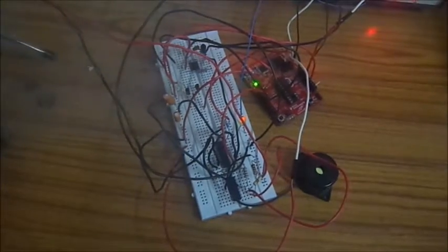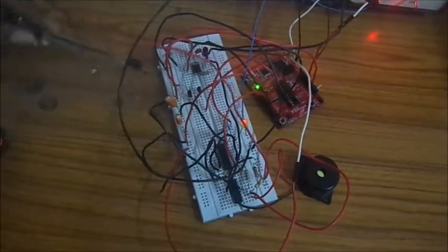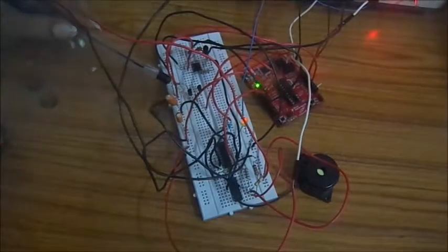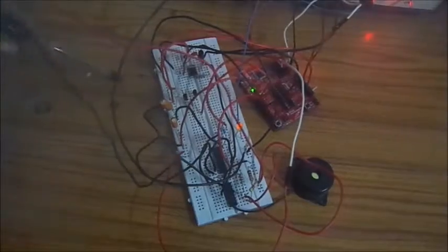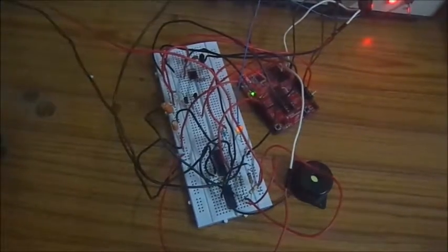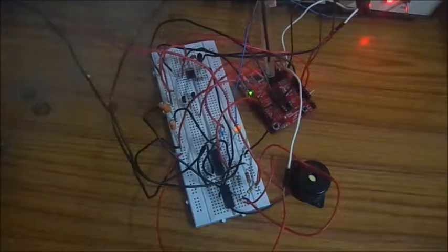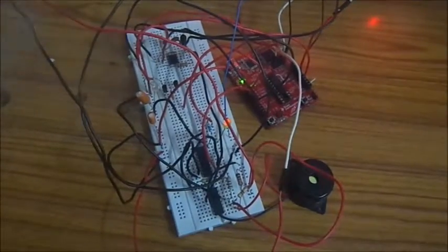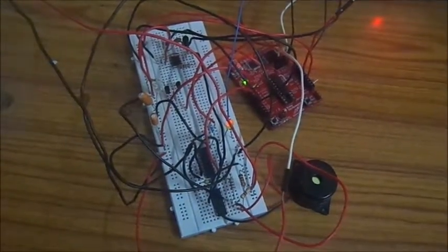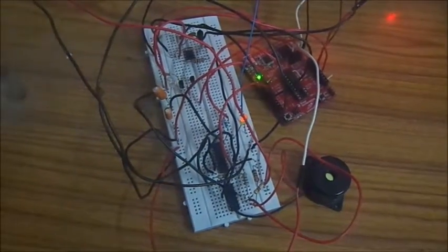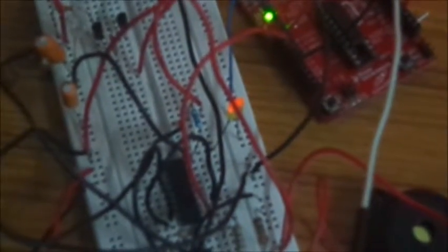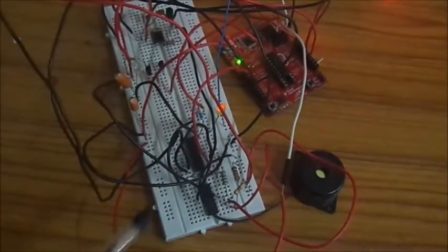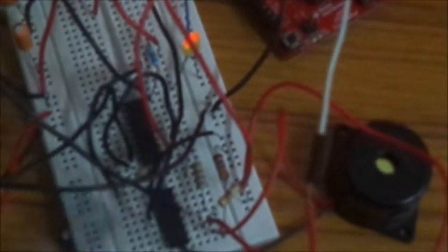Coming to smoke detector working, whenever smoke is present, the IR transmitter will transmit the information to the IR receiver, which is connected to the instrumentation amplifier. The output of the amplifier is given to the microcontroller's 6th pin as input, and reference voltage is given to the 7th pin as input. When smoke is detected, the output pin of the microcontroller will be pulled up as the indication. The smoke LED, which is connected to the second pin of the microcontroller, will glow. The fourth pin of the microcontroller is connected to the buzzer driving circuit, which blows the buzzer when smoke is present.